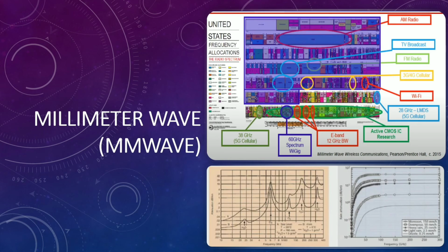This picture below shows the power attenuation, which is on the y-axis. Higher power attenuation means the worse it becomes. On the x-axis is the frequency. Based on the image, the attenuation is exceptionally high at 60 GHz due to the absorption from oxygen. In other cases, it has spikes when there is water.